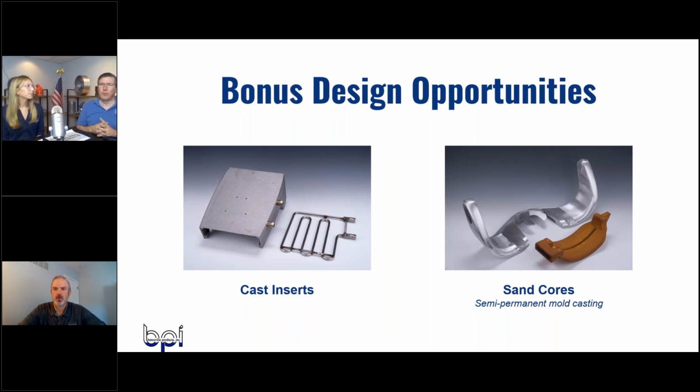Okay. Metal cores, there would be a separate slide that would insert that metal core in and then pull it back out before the die is opened up. But those sand cores can create quite a complex geometry inside of a part. Sure, yeah. So that you can be able to, whether it's run channeling, like wire channeling through it and such. Okay. Yeah. All right, cool.